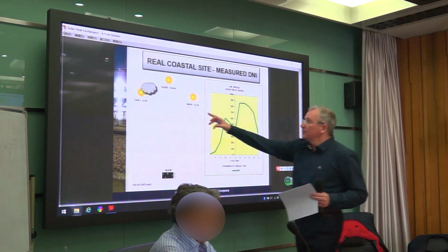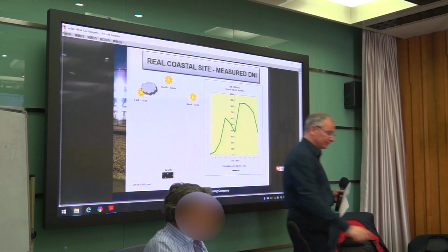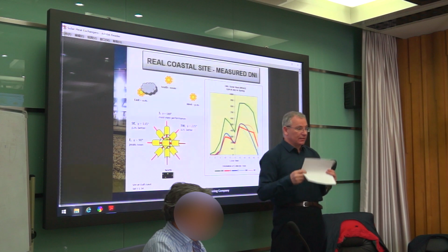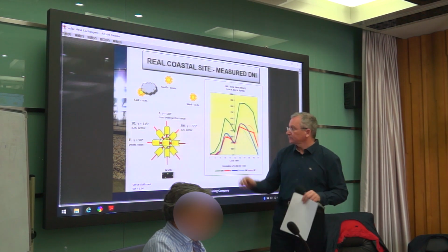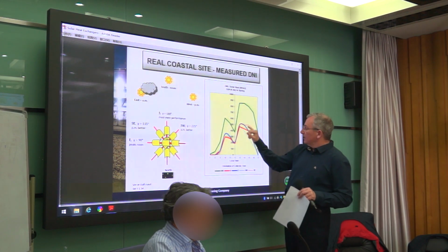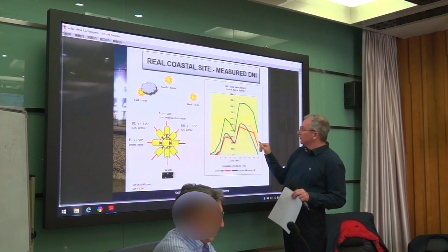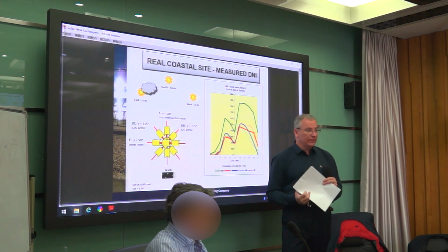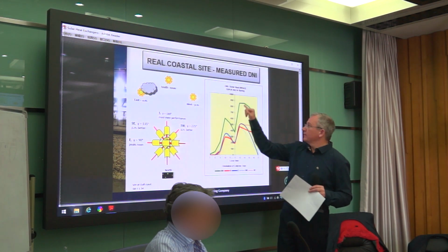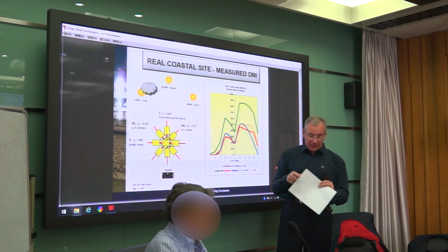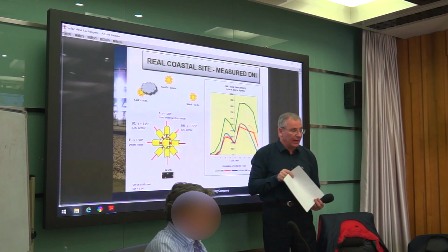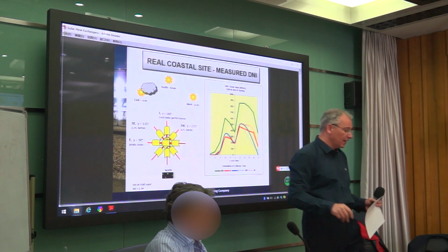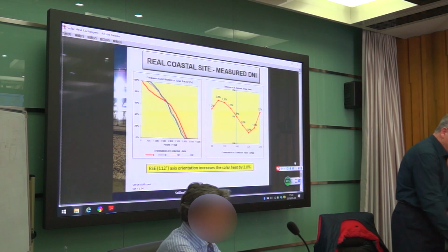As you can see, it's partially cloudy, as shown here. And we are plotting all the directions. Again, this direction, this direction, this, and this. As you can see, definitely the most preferable would be D1, which is facing the sun in the evening, because in the evening we have the highest radiation. Now we are looking for the precise angle, because it's not only 135, it could be 112 or 115, depending on where we are.